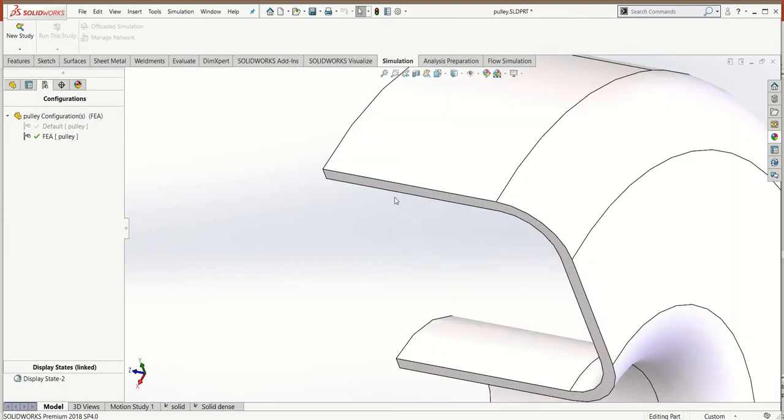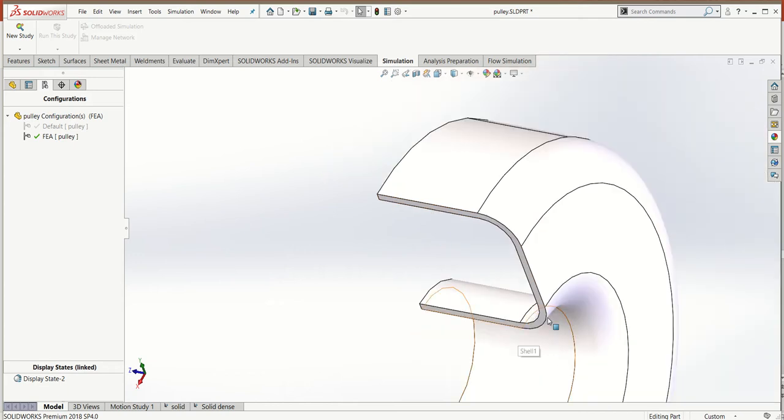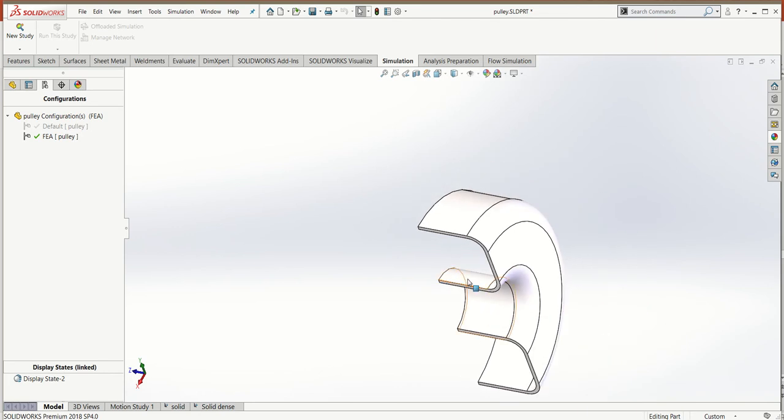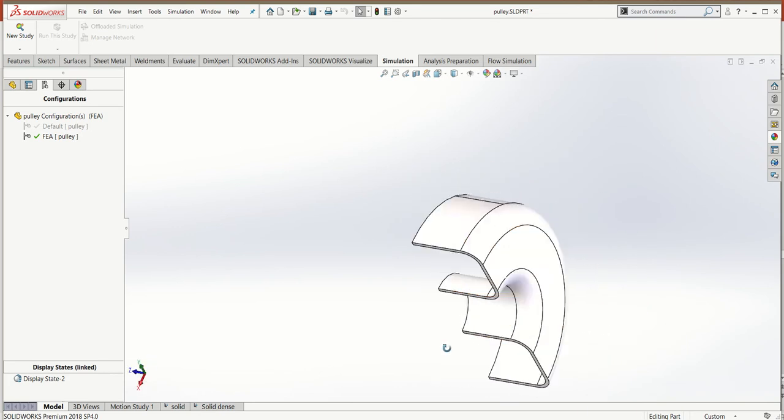Now what I am going to do, I will mesh a mid surface and run the analysis. Then I will select the outside surface and run the analysis, and we will see what the difference is and how it differs from your solid element result, and how much time it would take. And for exercise purposes you can go for an inner surface.